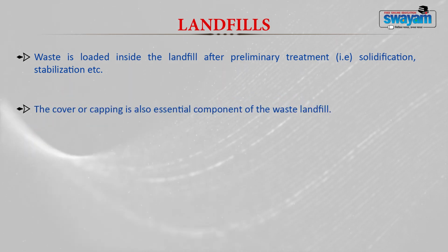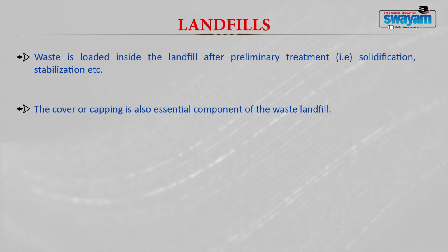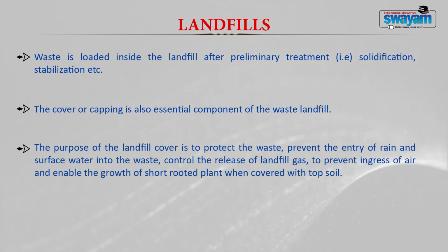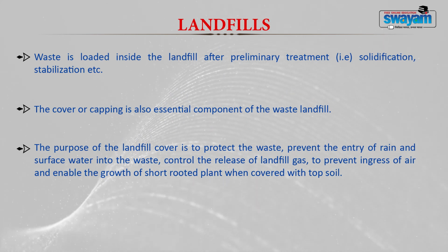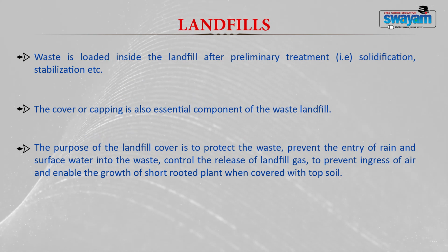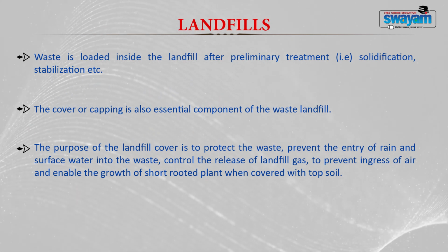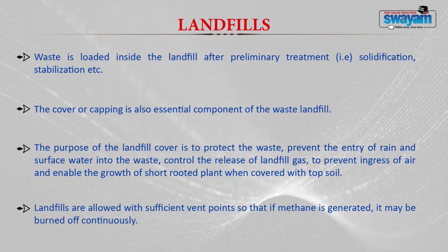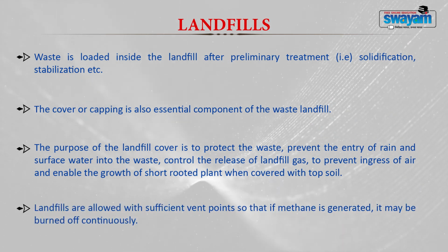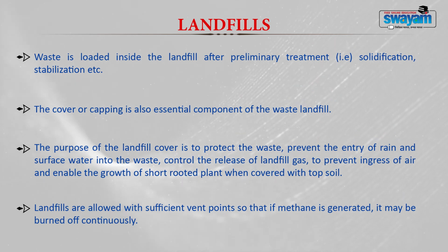As I told you, the third component is your cover or capping, which is very essential to contain your waste in the landfill. The purpose of the landfill cover is to protect the waste, prevent entry of rain and surface water into the waste, control the release of landfill gas, to prevent ingress of air and enable the growth of short rooted plants when covered with the topsoil. Now, landfills are generally allowed with sufficient vent points so that if methane is generated, it may be burnt off continuously.